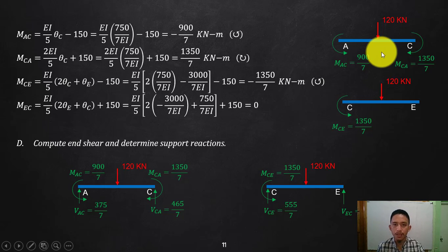Please differentiate that one. Fixed end moment is only to be used for the solution, which is what we will be doing, making both ends fixed and then solving for the moment. But what we need for the support calculation, or reaction calculation, is the actual end moments.